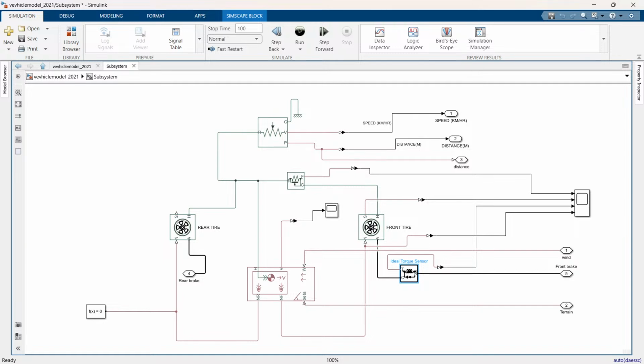The first ones are the conserving ports, port R and port C. Port R is connected to one side of the mechanical system where the torque is applied. Port C is connected to the other side of the mechanical system where the torque is being monitored. Port T is a physical signal port. This is the output port that gives the measured torque as a physical signal that can be used in other parts of our simulation.